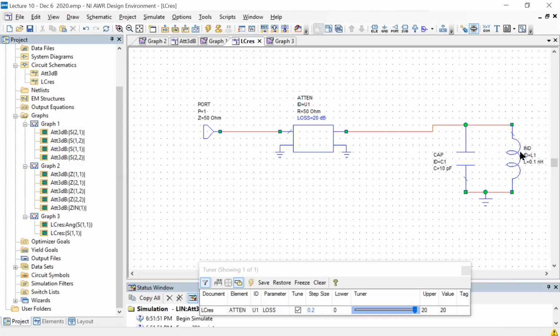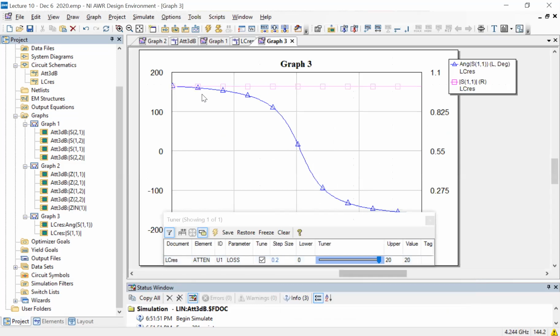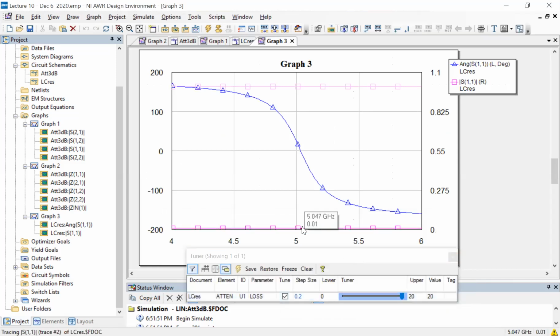But quite often in realistic devices, you cannot put too much power before the device starts to break. It could have some non-linearities, or there could even be heating. In fact, Jay and Sujita, we had discussed that we can't put these losses at low temperatures because then it will dissipate too much and heat the fridge. So here it's kind of misleading because the phase response is unperturbed. You don't see that things are going wrong, but with a 20 dB attenuator, you're going to get only 1% of the power which you send in back, and that can cause an issue.